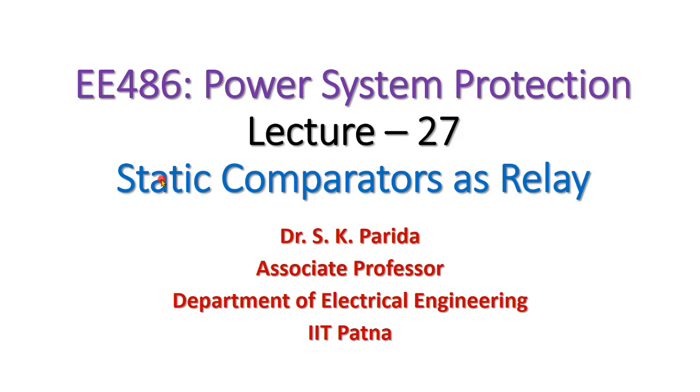We have seen this by adding and subtracting the phase comparator signals and providing them to the amplitude comparator. It will act exactly like the phase comparator. Similarly, the amplitude comparator, when implemented using a phase comparator, is the same, and this is the concept of duality between the phase comparator and the amplitude comparator.